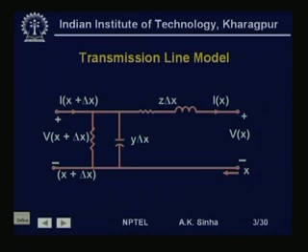Well, as we have seen in our previous lessons, when we discussed the calculation for transmission line parameters, we found that transmission lines have in general 3 parameters: the line resistance, the line inductance and a capacitance of the line to the neutral or ground. Now, as we had seen in the previous lesson, these parameters are distributed all along the line. That is, if we see a line, it will be something like this, where I have taken a small section of a line.